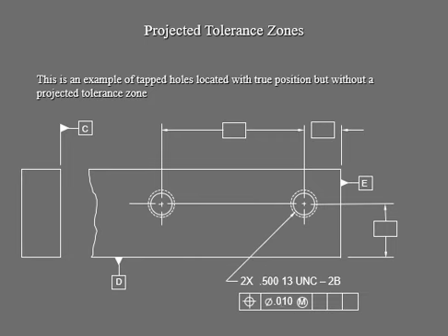Okay, so here I come back to here. Here is your feature control frame, giving you the position tolerance of 0.01, and then we have a thread note right there, major diameter 0.5, and you have 2 of them. So that's 2 times, with 13 threads per inch, and we're doing a coarse thread for this part. So that's your UNC. This is your thread note. If you need to review, go back to MAT 101. And here is your identification of your internal or external thread, A and B.